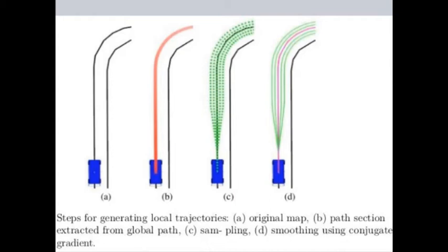It will always tell the car to stay in the center of the lane, and then the rollouts guarantee a possibility for evasive maneuvers. These are the rollouts that the Open Planner produces using the local planner. So if an obstacle is in the center, the car is going to use a left or right rollout to deviate from the obstacle.